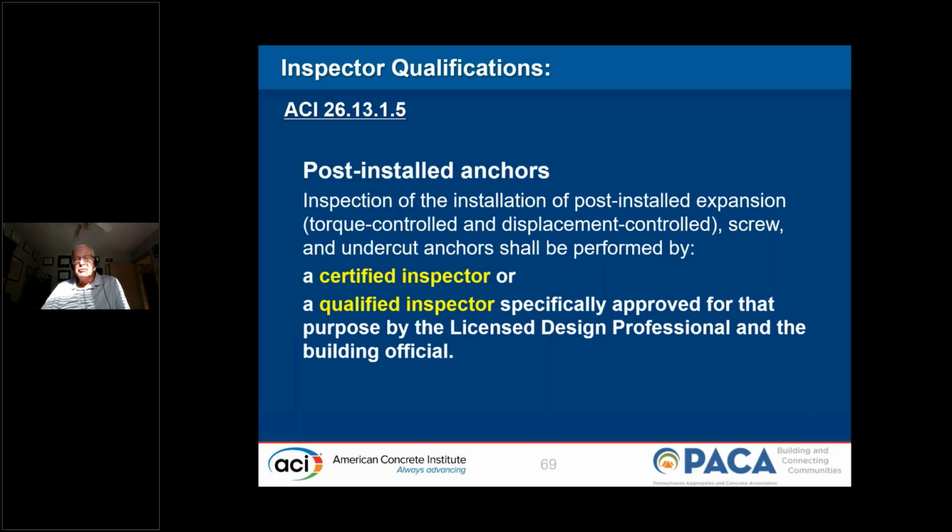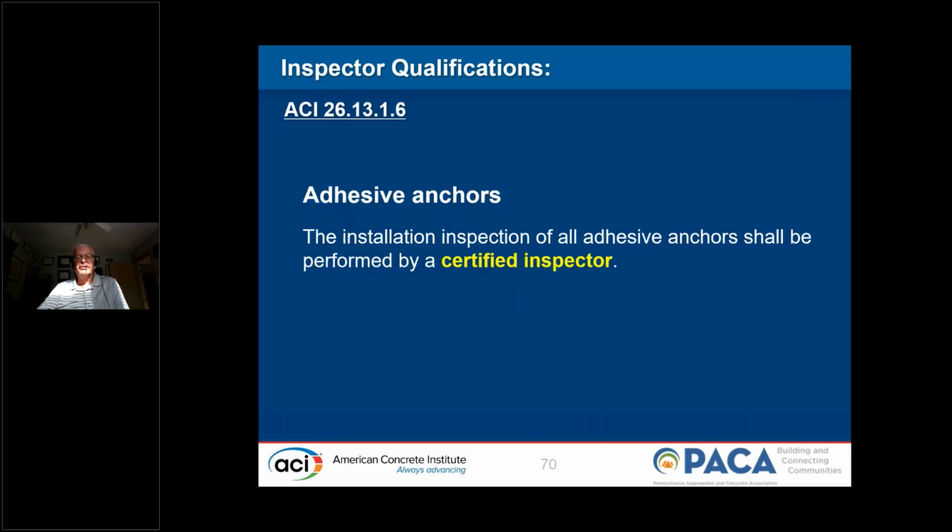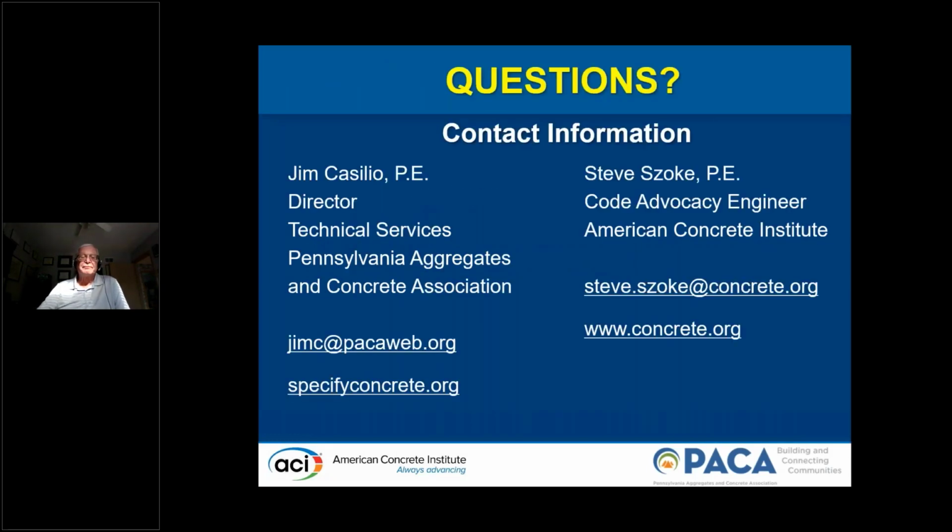When it comes to post-installed anchors, the inspectors should be a qualified inspector or the licensed design professional or a certified inspector. That's for all post-installed anchors. If they're adhesive anchors, then they must be inspected by a certified anchor inspector.